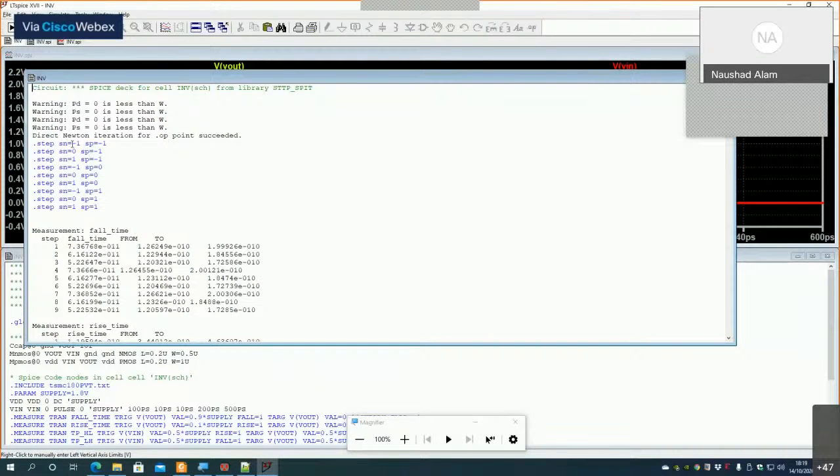Now you can see how it has varied the speed parameters of the NMOSFET and PMOSFET. First, -1, so what it means, slow N, slow P, or SS. Okay, nominal N and slow P, fast N, slow P. Then you have slow N, nominal P. Is it visible or shall I magnify? Is visible. Okay.